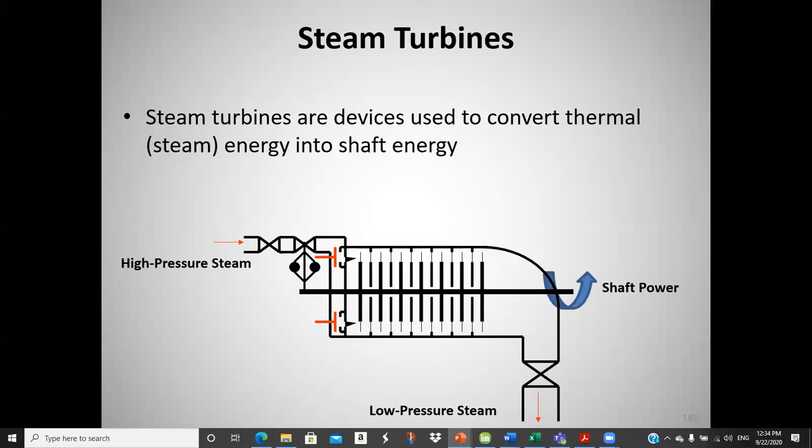It would spin around, geared to the shaft. It's set so that when it's going the right speed, the centrifugal force pulls those balls out a certain amount, and that controls the steam valve through linkages. If it starts going too fast, they go out too far, and then they'll cut back on the steam a little bit. So that thing adjusts. That's a pretty good depiction, better than I could draw, of a governor.